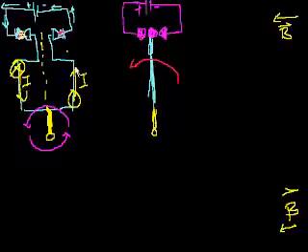kind of, so this side right here, let me do it in a different color so you can see it. This side is this side, right on top, and this side is on bottom, below the page. This side is now above the page, right? If this distance is r, this side is now r units above the page. And I said, ideally maybe your commutator loses touch with the brushes at this point, right? Because they're popping out a little bit, so when you're vertical, they actually lose touch with the brushes.